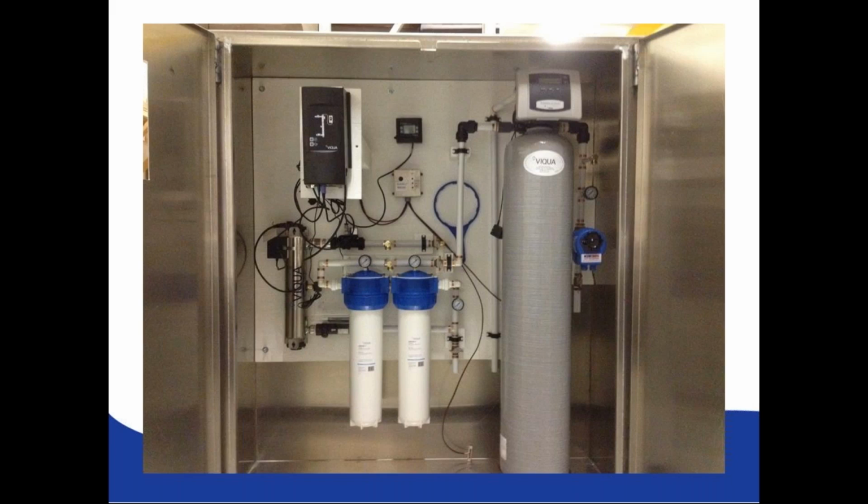And if you have a UV system with a flow meter, it's very important that you have a non-turbulent flow. So down on the bottom right of the UV chamber, you'll see a black device. That's actually a flow meter in this case. We have a nice straight length of pipe going into that flow meter so that we have laminar flow so that flow meter can read accurately. If we were to have an elbow immediately before that flow meter, it might not read very accurately, and it might interfere with our dosage monitoring.